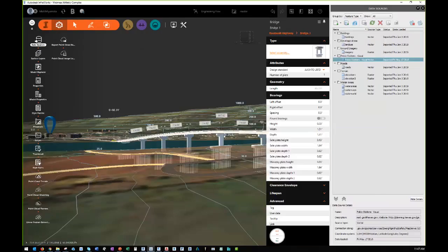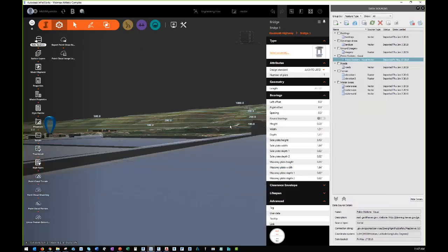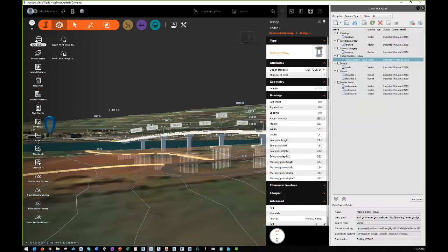You have to click on the right component. So if I have the girder selected, but I made a change to the bridge tab, then those changes aren't going to be quite correct. But once I have that component selected correctly, I can update the existing. And when we make the update to the existing, that tooltip that I applied there in the spreadsheet now appears as a tooltip for that component inside of the drawing. So that was a very, very basic modification that I made, but you can see that it is linked to that spreadsheet that was exported out and